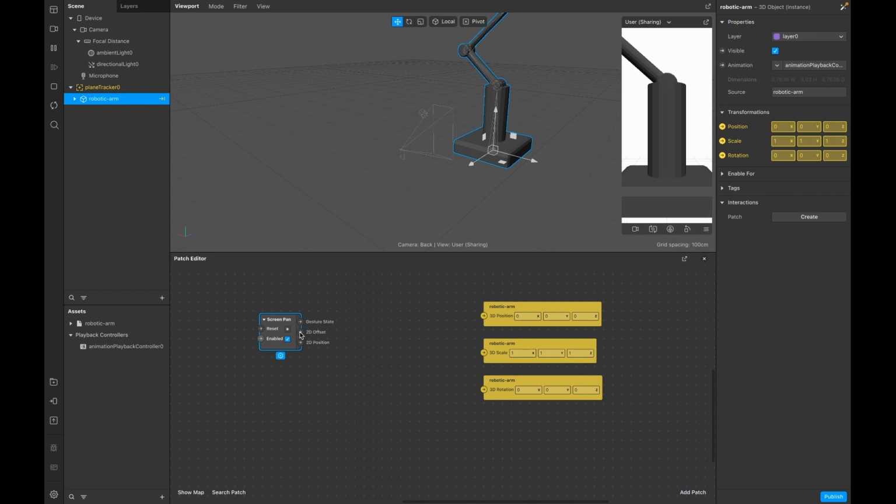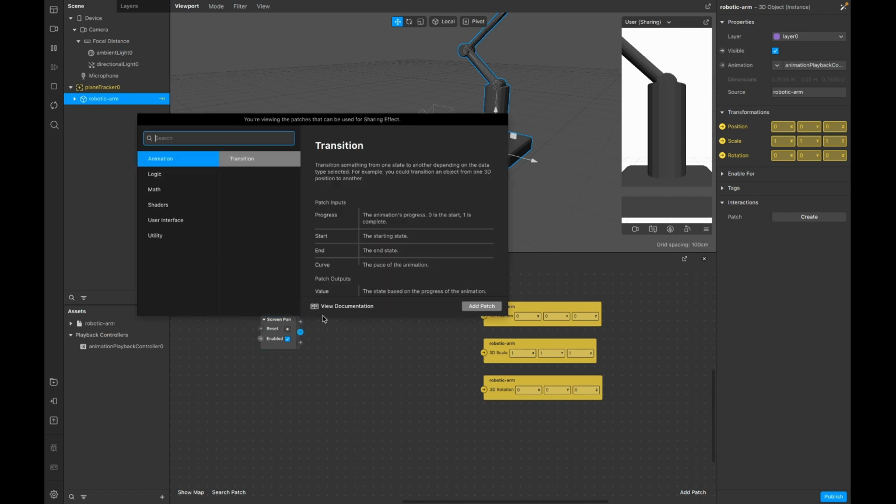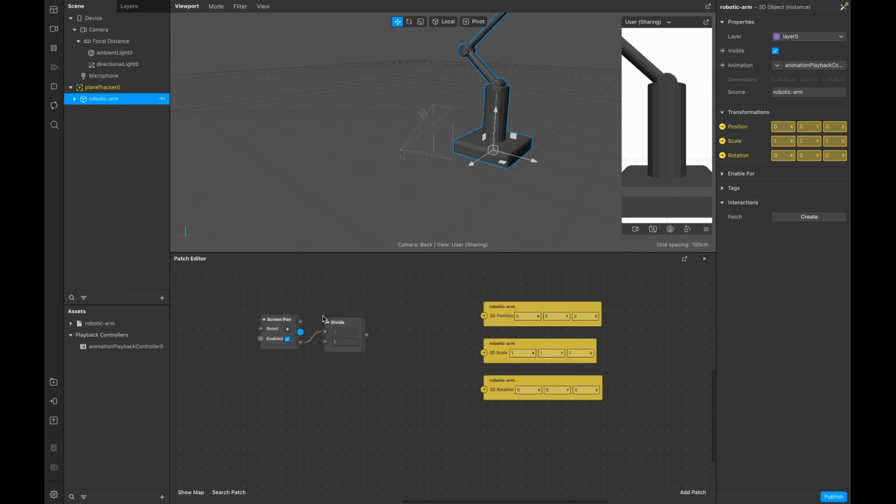The values returned by this patch are too high and will cause our object to move very drastically in the scene. To achieve a smoother movement, we need to divide these values by another number. In this case, we use 900, but 1000 works perfectly fine too. That is up to you. Just remember that we need values lower than the original ones.